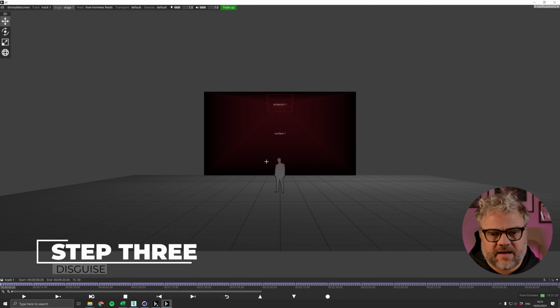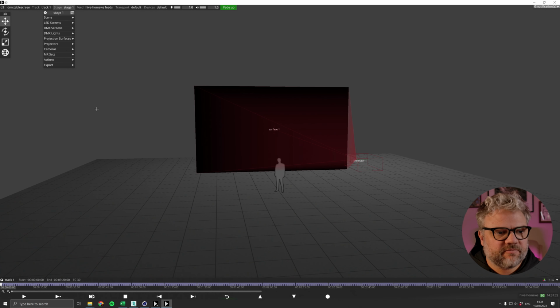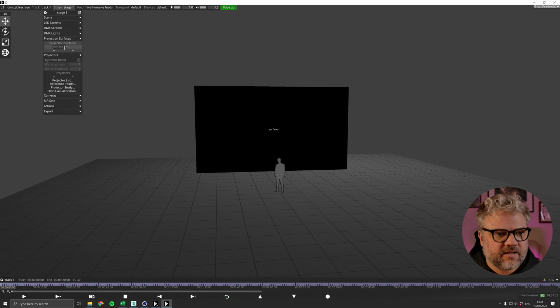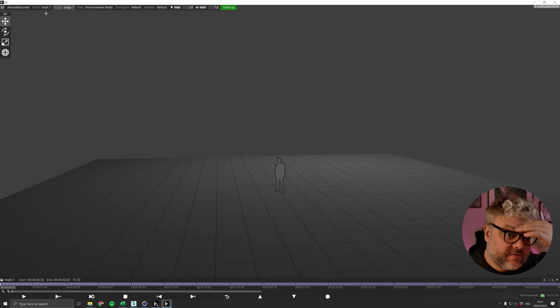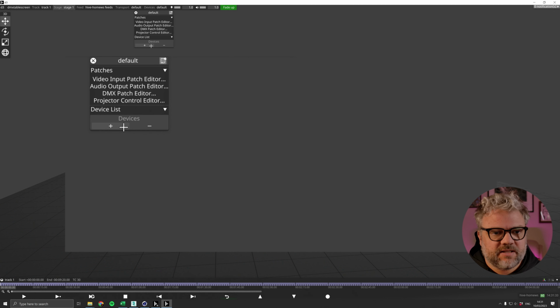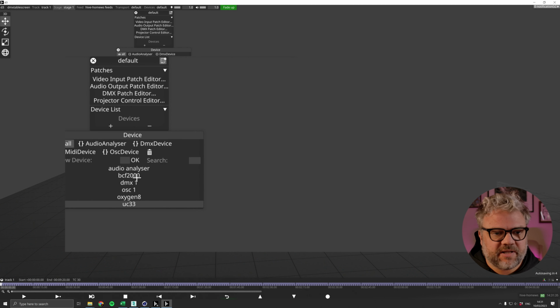Let's just do a little bit of housekeeping to a new project. We don't really need our projector or our surface, so let's take those out. In order for any DMX data to be able to leave your system, you need to add a DMX device to your device menu. So there's a default one there already created for you.